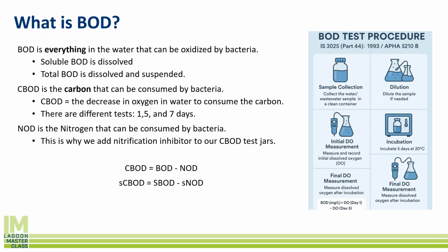The procedure for CBOD testing is exactly the same as what you see on that screen, except before we put it into the incubator, we actually add a little bit of nitrification inhibitor that makes sure that the nitrifying bugs can't actually convert ammonia into nitrate, because that would consume oxygen. So that's the big difference in that particular step, is that we're actually adding an inhibitor.